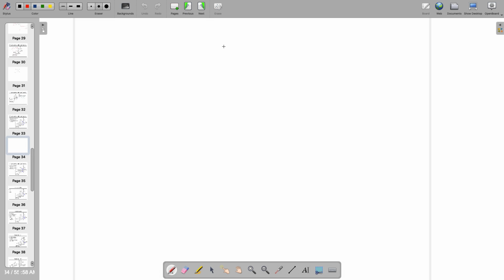So if this is a current source as a load, and there is a transistor whose name is M1, and two resistances biasing the gate potential with a coupling capacitor, we are doing this. And when we are doing this at high frequency, this is a short circuit, by the way, because this is a big capacitor, so it will be shorted.